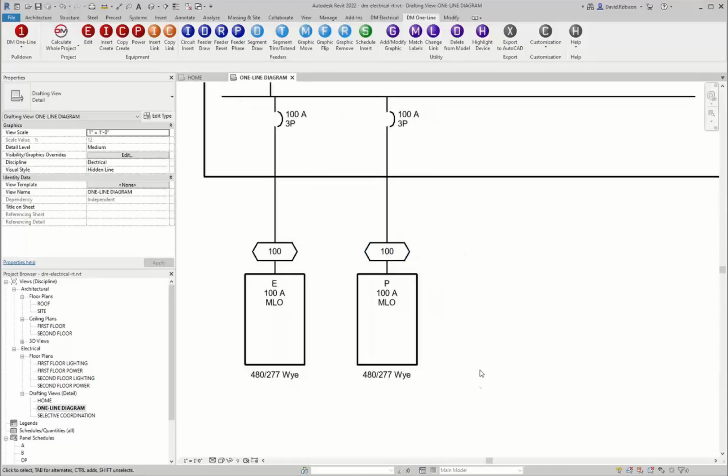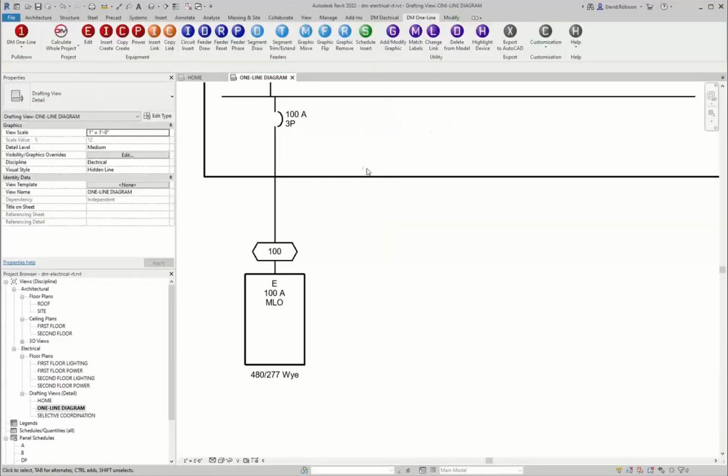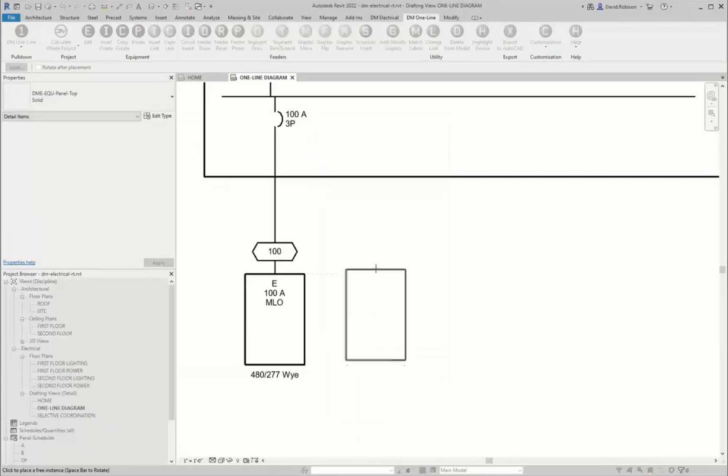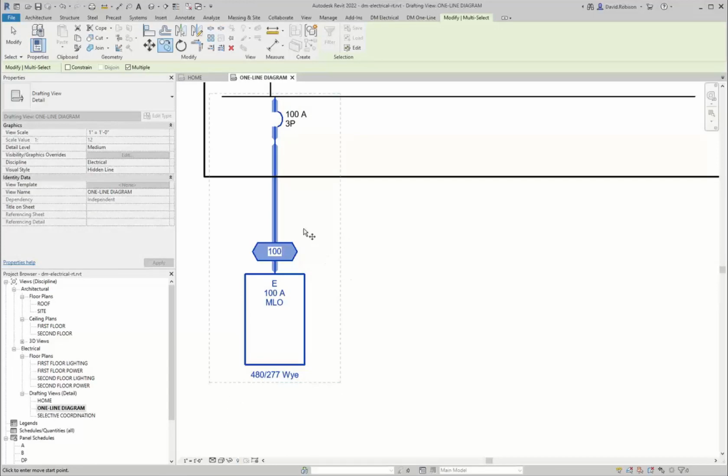You also can use Revit itself to make the copy. With our copy link, you'll see that it's coming in, and the insertion point is the base insertion point of that family, which sometimes works and sometimes is not what you want to use as the base point. You can use the standard Revit copy command, and now you can actually specify a base point. So say we wanted to actually use this point here as the base point, or we wanted to have it offset the same distance from here to the next one, we could choose that, and then you can choose your other base point. So now you can use the Revit base points to make the copy.